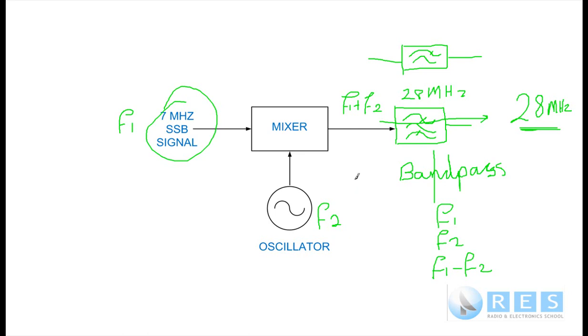So we will do this in a transceiver many times, and after the bandpass filter we're going to have a pretty weak signal here, so we would put another amplifier, an RF amplifier. But we'll be talking about block diagrams of transceivers, we might be talking about it a little bit in this tutorial, but we'll certainly be talking in depth about single sideband and FM later on. In depth to the standard level anyway.